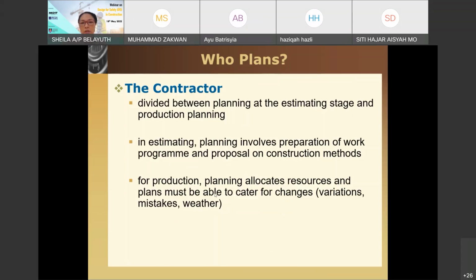Would be during construction because the planning is where you're talking about so many elements joined together. You have architecture coming in, structural, M&E coming in, but you need to know which comes after which. Structure dulu ke, architect dulu ke, M&E dulu ke, or it is together. And even structure, you might be having column here, and then you might be constructing slab there. You can't wait for A to finish, B start, B finish, C start one by one. If you're going to do one by one throughout the construction, it will take forever. So you would have activity whereby you start together, you start together after a few days. So the sequence of the activity is very important.